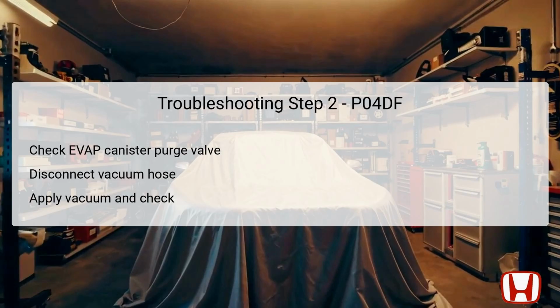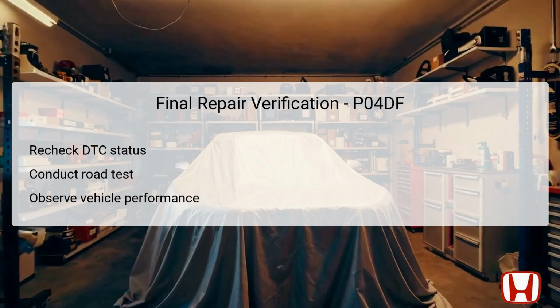At this point, carefully observe if the valve holds vacuum. If it successfully retains the vacuum, this indicates that the EVAP canister vent shut valve likely requires replacement. However, if it does not hold vacuum, you will then need to replace the EVAP canister purge valve itself, as it may be faulty.